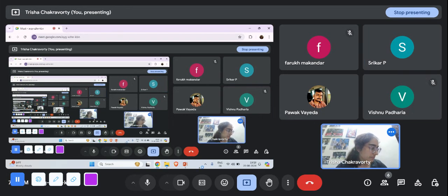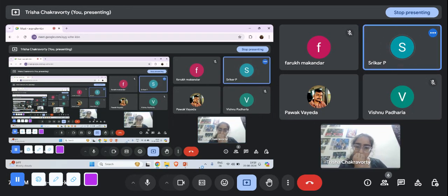Okay, ask now. Particularly, you have explained about the black bolts and the friction grip bolts, and the formula related to that. Friction grip bolts have the advantage of friction, and you are using the mu formula. That is all good, but how exactly? Because that seems to be friction between the plates. The bolt is not actually doing anything with respect to the friction. I feel even with the black bolts, if it is tightened a little more, the same kind of tightness can also be observed. So how exactly are friction grip bolts providing the friction strength?